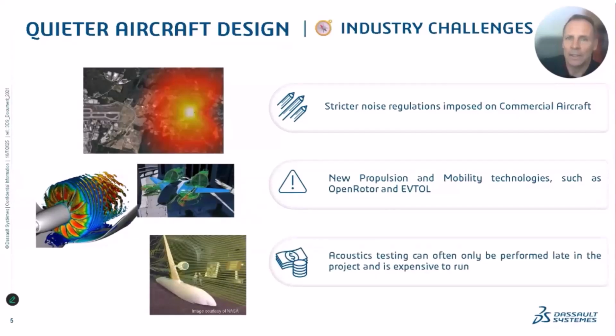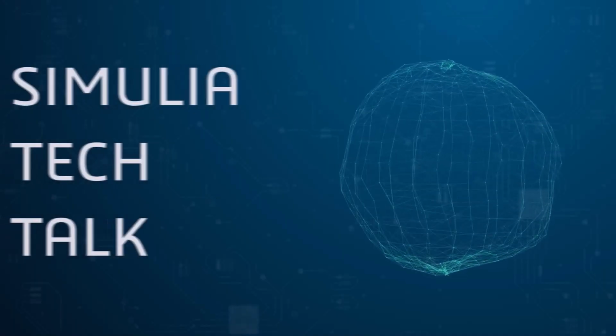And thirdly, to address these challenges with physical testing is quite difficult and expensive. Wind tunnel tests can generally only be performed at model scales that may or may not correctly capture all noise generating mechanisms, and flight testing can obviously be done only very late in the process. It's also very expensive, but that late in the process it's very expensive to fix noise issues.